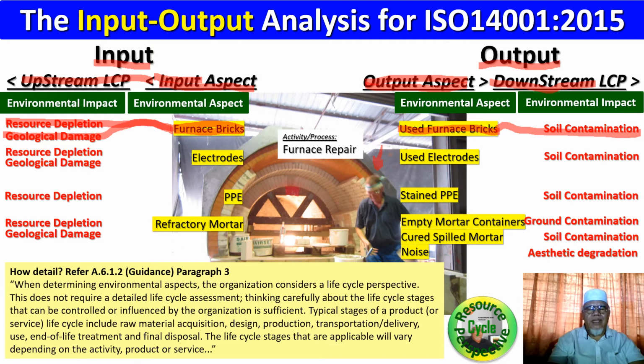It will have most of its outer surface disintegrated due to the action of the various sorts of materials in the secure landfill, and eventually it produces leachate, and therefore it will leach out, and a secure landfill is not 100% secure because the earth is moving, is vibrating, and hopefully not, but from past records, we have seen that there are cracks at secure landfills, and eventually it will contaminate the soil or even pass down through the vadose zone and find itself into the aquifer and perhaps contaminate groundwater. That could be the eventual environmental impact, but I didn't write down groundwater contamination there because I'm not given the evidence.